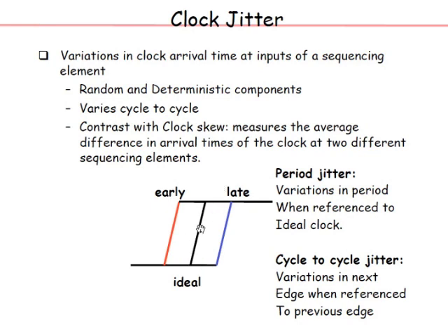But what happens is that because there is something called jitter, you'll find the clock edge sometimes happening earlier, sometimes happening later. That means the period of the clock on average is Tc, but cycle to cycle there can be small variations. It can be a little less than Tc, it can be bigger than Tc, it will keep on fluctuating. Okay, it's a statistical process, it's a random variable. The clock period is a random variable. So this is basically what happens.